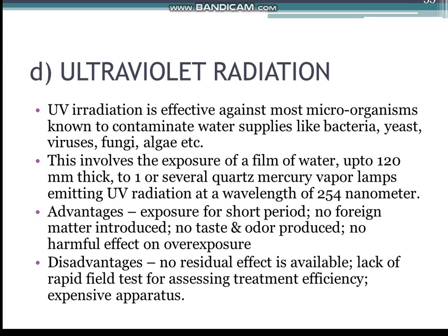Ultraviolet radiation. Germicidal property of UV rays have been recognized for many years. UV irradiation is effective against most microorganisms known to contaminate water supplies like bacteria, yeast, viruses, fungi, algae, protozoa, etc. This method of disinfection involves the exposure of a film of water up to about 120 mm thick to one or several quartz mercury arc lamps emitting UV radiation at a wavelength of 254 nanometer.